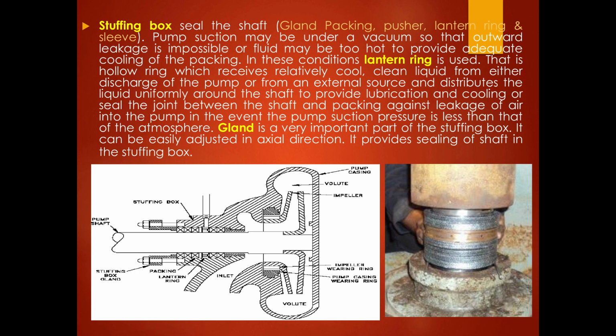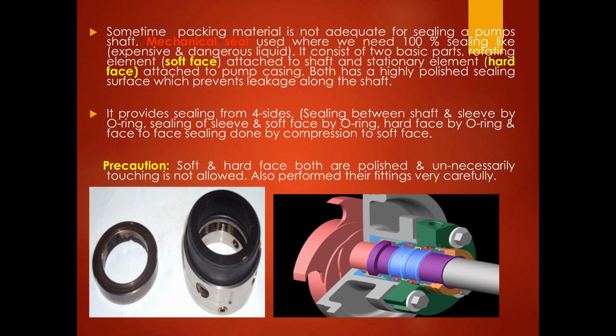It can be easily adjusted in the axial direction. It provides sealing of the shaft in the stuffing box. Sometimes packing material is not adequate for sealing a pump shaft. A mechanical seal is used where we need 100% sealing, like for expensive and dangerous liquids.